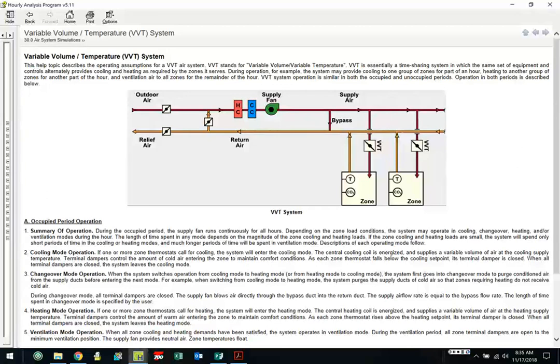So how this system works is simple. I've got a bunch of boxes. Again, let's talk about 5 of them. Let's say that out of the 5 boxes that are on this, that are down here a little bit, 3 of these boxes are calling for heating right now. These 2 are not calling for heating or cooling. So what happens is the control system would index the unit and say, let's go to heat because I've got 3 zones that need heat.